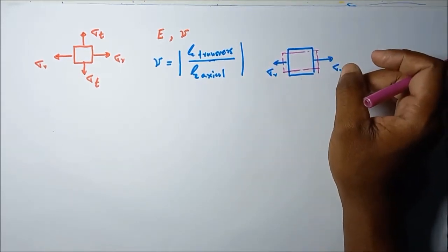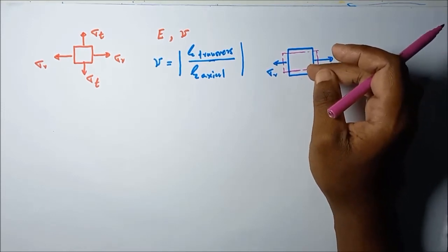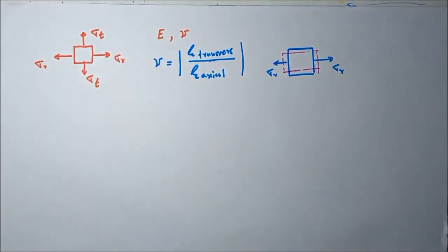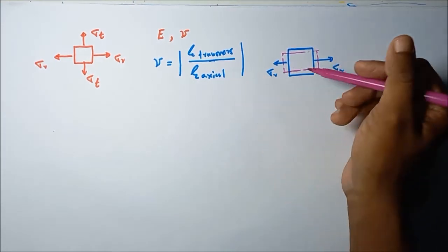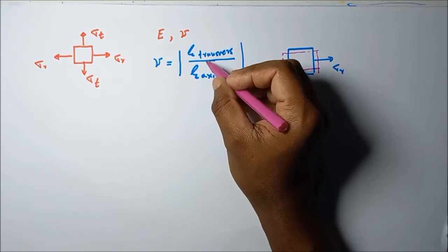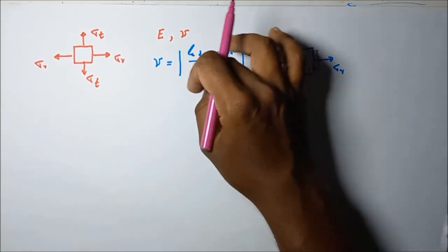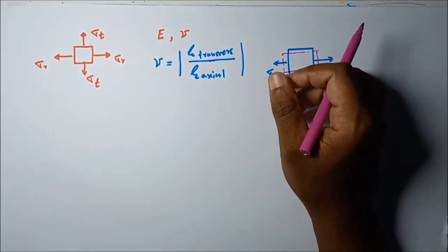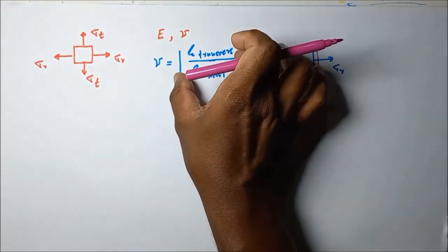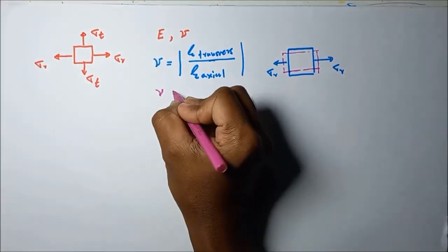It is a material property; it varies from material to material. For elastic plastic-like material, the Poisson ratio is very high. At this level you should know this ratio. You can see these strains are in two different directions: one is contracting, one is extending. So this ratio is always negative for a biaxial stress system. To remove this negative sign, we multiply with a minus sign.